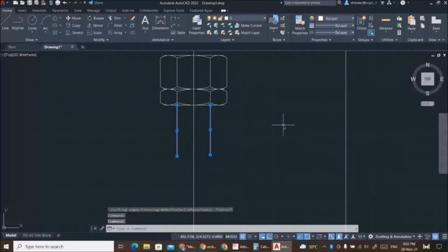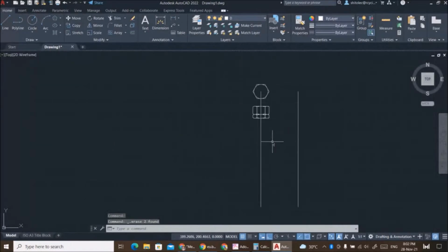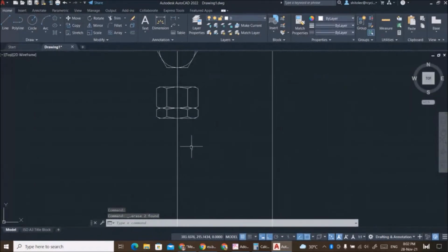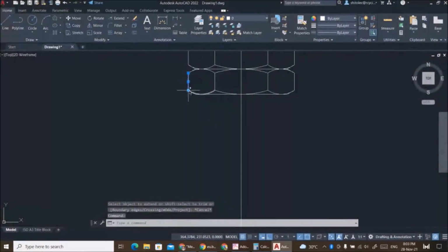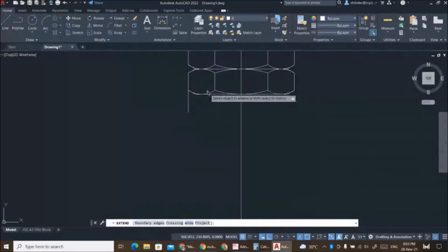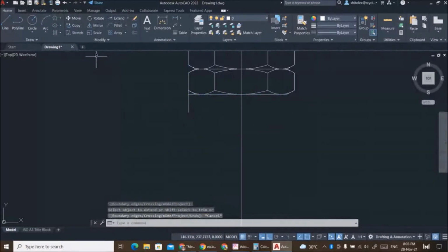So this line is noted. So as you draw this line, this line will extend and this radius is 3. So I will move towards left 3 and then come down 15. Okay, so we'll start from that point. Okay, make it like this. Escape and extend this line.